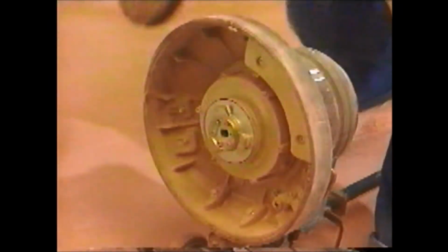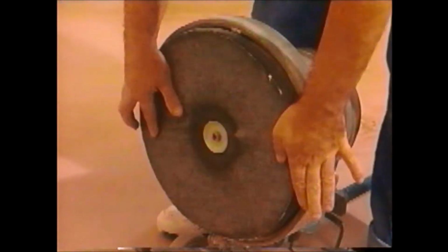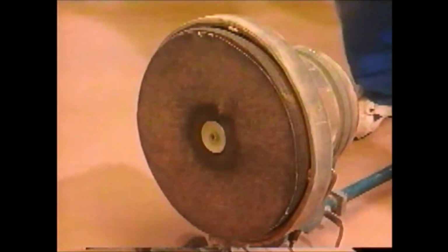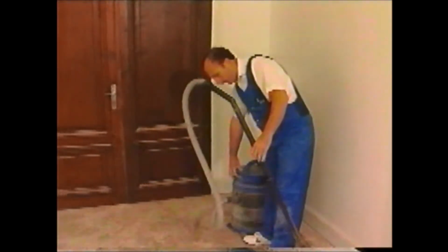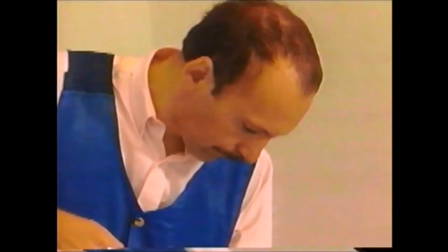Use a roller to eliminate air bubbles from the coating and level the finish. After a drying period of 24 to 48 hours, depending on the weather conditions and according to the instructions on the bag, sand the finish to eliminate all traces of slurry deposits and any uneven spots. Sweep and vacuum to ensure proper bonding of the glue. The subfloor is then ready for installation of the floor covering.